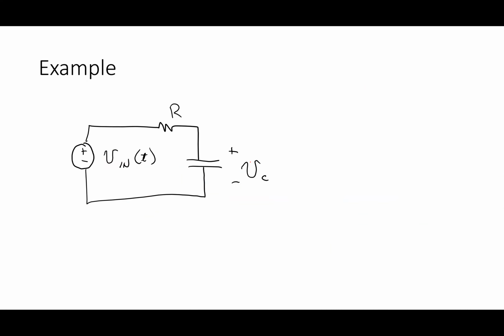I want to deal with looking at this particular circuit, and I want to figure out how we solve the differential equation that's going to come out from this. So, RC circuit, voltage source input like this. What's the thing you typically end up solving for in a circuit like this? It's the capacitor voltage, right? So in this case, how do I write the differential equation? What's the process to start for solving this?